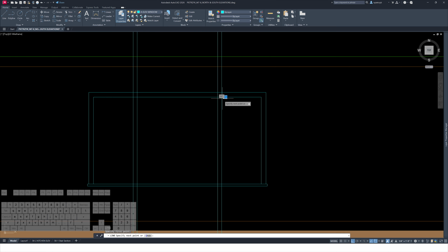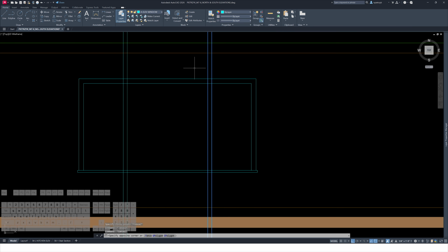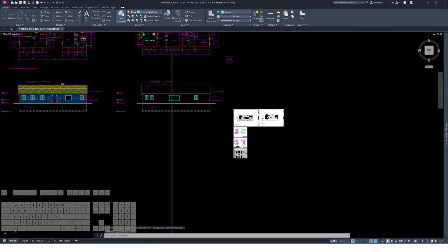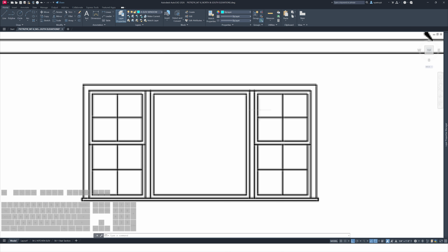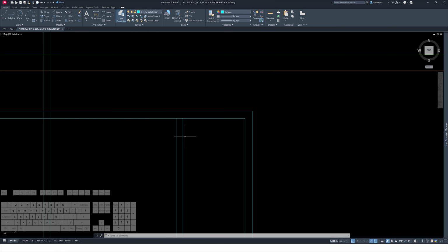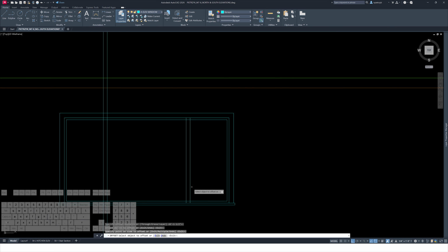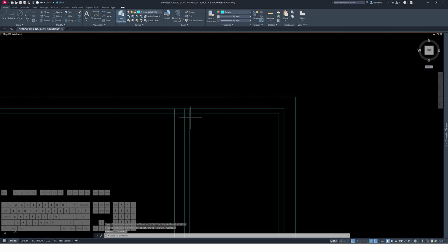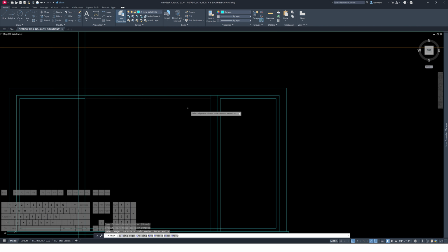I'm going to draw a line at this point here and here. I'm actually going to work on this one, and then I'm going to mirror it over. And I'm going to just consult my page here, just to make sure things are looking good. Yeah, so this is how it's supposed to end up looking. And so far, so good. I'm going to offset by 1.5 inches. And I'm okay with that going all the way around. Offset that in there. I'm going to trim this corner and this piece, because this interior one needs to be this as well.